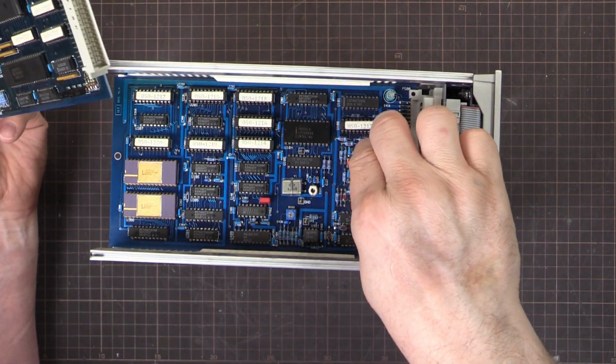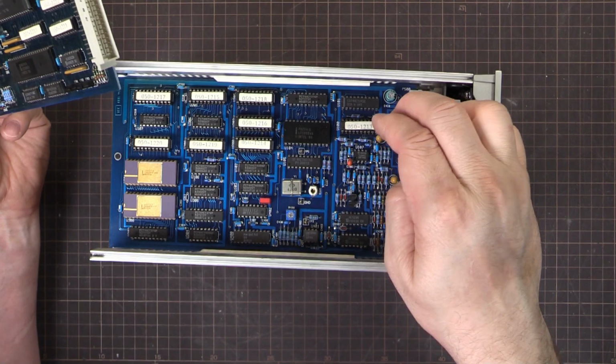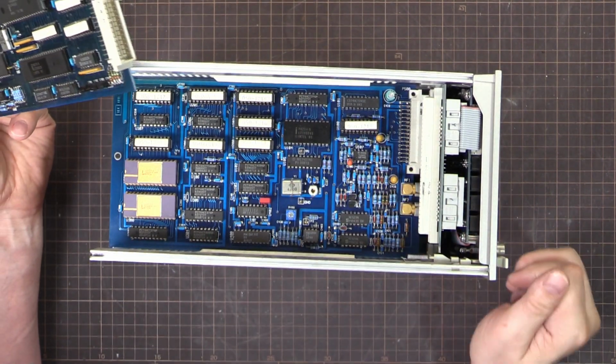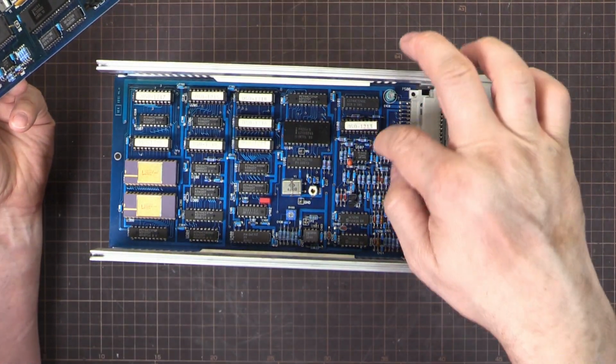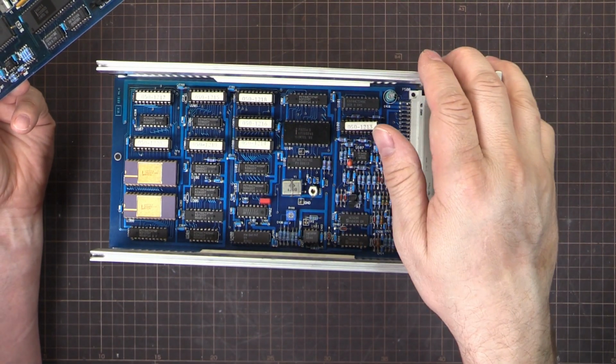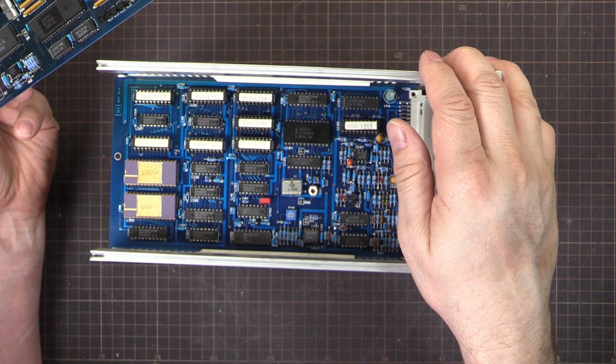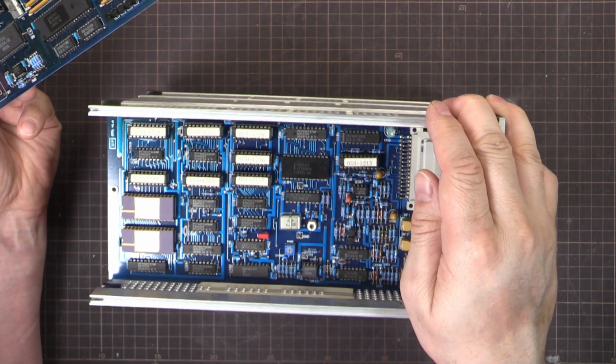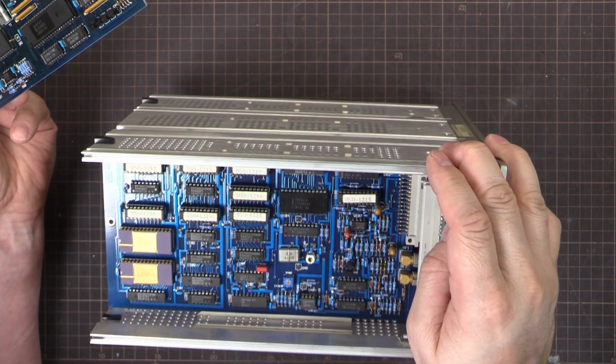You can check them with your multimeter. Make sure you get the polarity correct, because tants don't like being reverse biased. They're marked with a positive lead, and you test that, and as long as they don't have a resistance down in the single digit ohms, or even low double digits, they're probably okay.